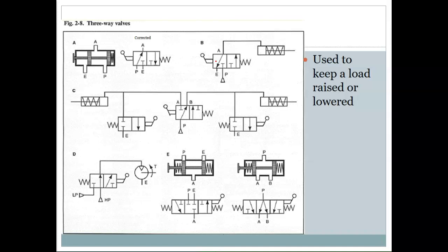Now, I will say this because it is a test question and you might want to know it. You see a spring on either side of a valve. It means that A, it's got 3 positions, and B, it is what is called spring centered, which means that when no pressure is applied, it goes to your center set as your main way you're supposed to see the valve, or the main way it's supposed to live.